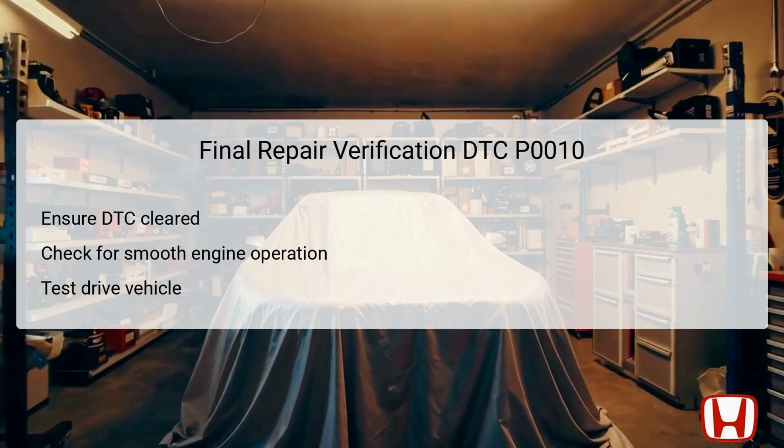Begin by clearing any stored DTCs using the HDS, ensuring the engine control module, ECM, has a clean slate to work with. Next, start the engine and monitor its operation for any rough idling or abnormal noises. Confirm that the engine runs smoothly without issues related to timing or performance, indicating successful intervention. Finally, perform a test drive under varied conditions to confirm no new DTCs arise during operation and that the vehicle operates reliably. Successful completion of these steps denotes effective resolution of the DTC, ensuring optimal engine efficiency moving forward.